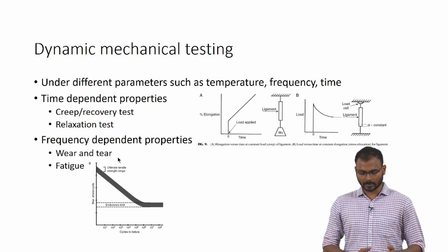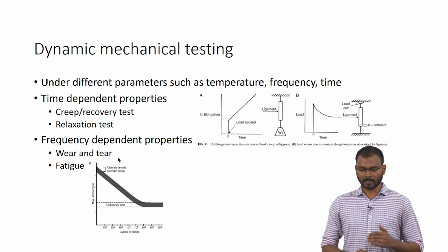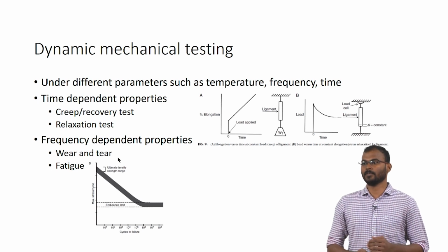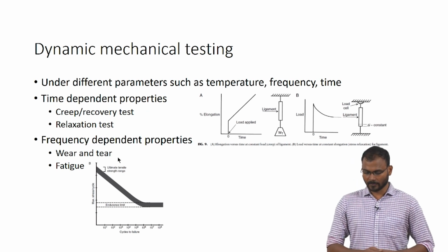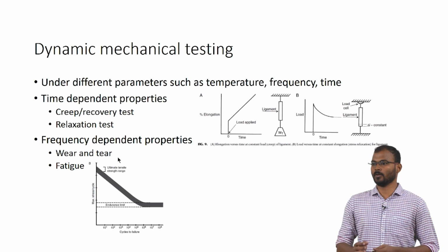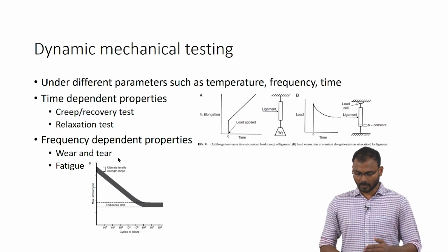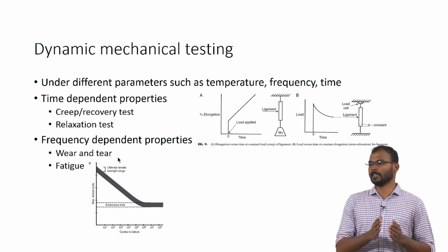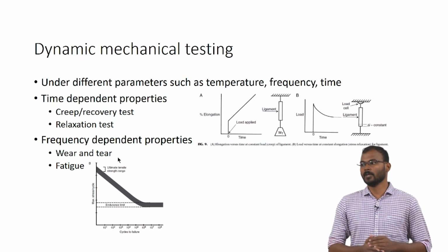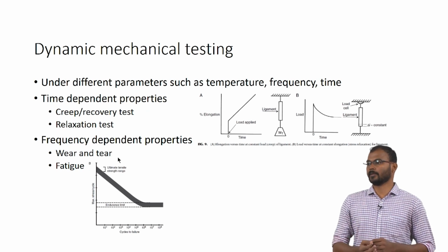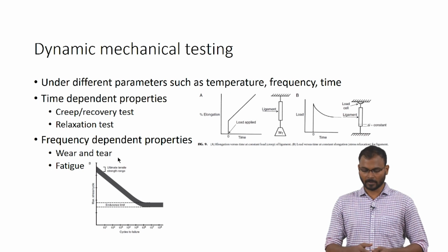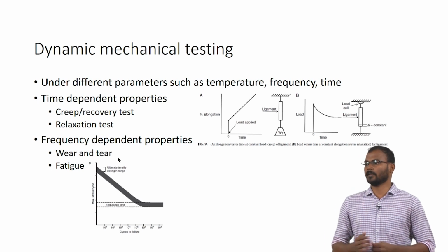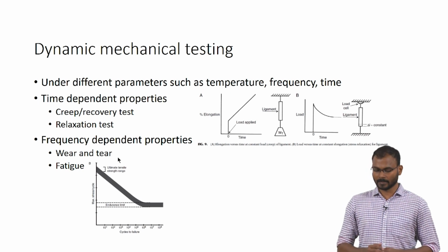In the creep or recovery test, the stress is maintained constant, whereas the strain would vary. If you consider a ligament, as you can see in the figure, the weight Wt has been loaded, that is, the load has been given. When it is given at the time point t, it will not elongate if it is within the linear range of the stress strain curve. After a particular period of time, it tends to elongate. So, that percentage elongation is changing. That shows how much time can affect the strain under a constant stress. So, that is the creep or recovery test.